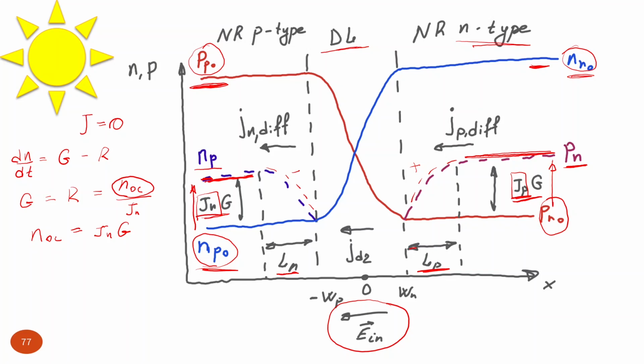So it creates this drift current, and the more it extracts, the more it will be reducing its concentration next to the p-n junction edge. And that's why we will create some gradient of concentration of minority non-equilibrium photo-generated charge carriers next to the edges of the p-n junction.